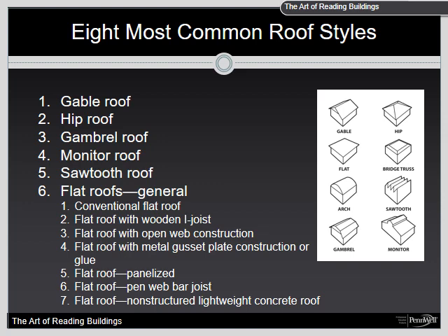Hazards. Although the roof is strong, items of consideration are the span of the roof and what holds the roof up. Common vertical structure members are hollow 4-inch steel pipes and wood members. Lightweight concrete roofs are difficult to penetrate without specific equipment. Masonry blades are ineffective, so ventilation may require the use of a rotary saw with a carbide tip, wood blade, or multi-use blade. A chainsaw equipped with a carbide chain will also work but can be detrimental to the saw.